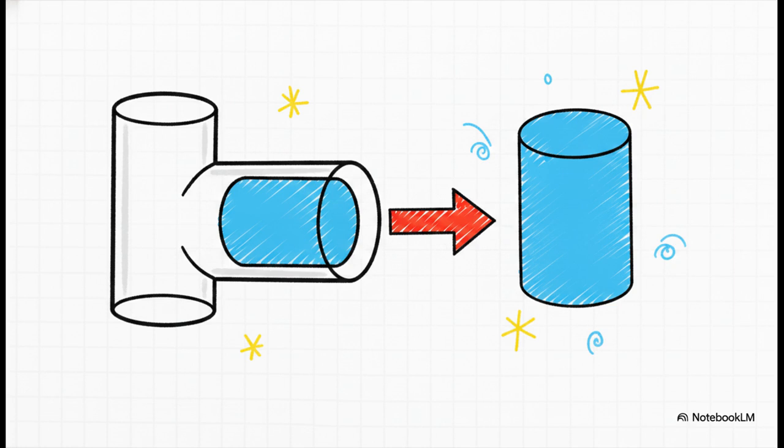To do this for an internal flow, say water running through a pipe, you define a seed face on the inside and specify your boundary faces. The software then builds the fluid domain that the physics will actually act upon.